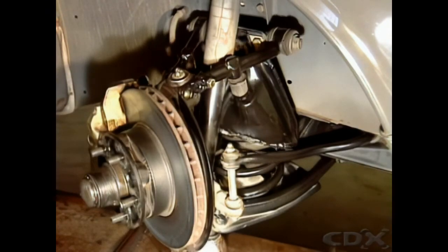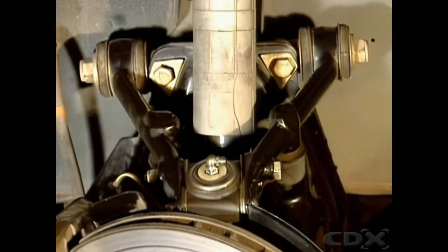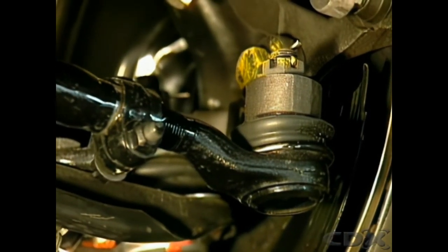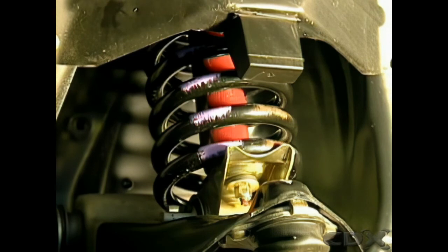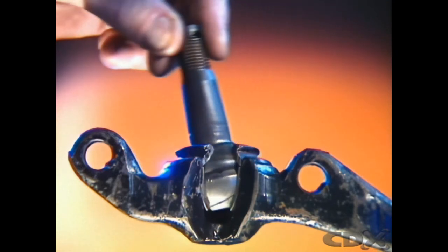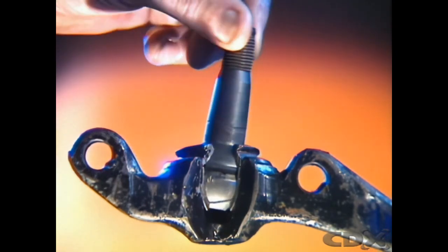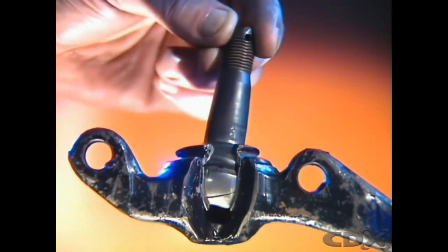Ball joints are swivel connections mounted in the outer ends of the front control arms and on the steering track rods and tie rods. They allow the control arms to move up and down with suspension deflection and also let the wheel and hub assembly turn for steering. The ball joint can be a sealed, self-contained unit fastened to the control arm in a number of ways. It is made up of a pressed steel housing, fitted with sintered iron seats and a hardened ball stud.